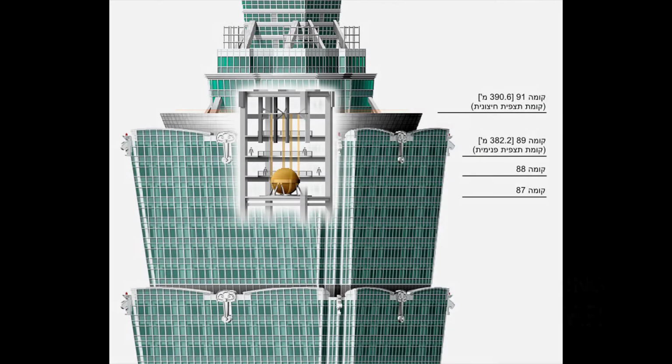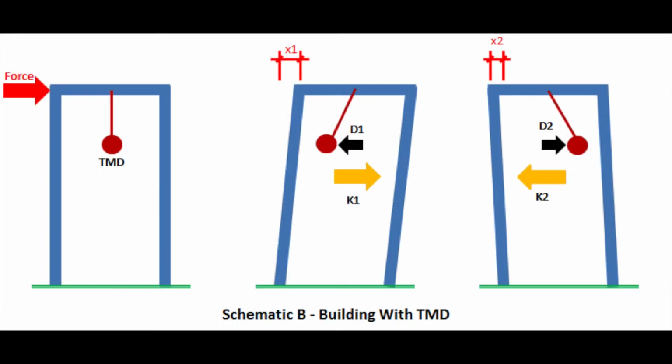For the final case, we will be looking at the damping mechanism using pendulum power. One of the damping methods that can be implemented is known as pendulum power, used primarily in skyscrapers and high-rise buildings. Engineers suspend a large ball with steel cables with a system of hydraulics at the top of the building. When the building begins to sway, the ball acts as a pendulum and moves in the opposite direction to stabilize the oscillation. Like damping, these features are tuned to match and counteract the building's frequency in the event of an earthquake.